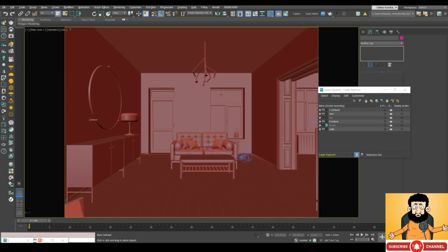And so finally, I'd like to talk about poly count. Now, poly count shows the number of polygons in the scene. So if I press 7 and see the total number of polygons that our scene has, it often happens that some high poly object is making the scene too heavy.